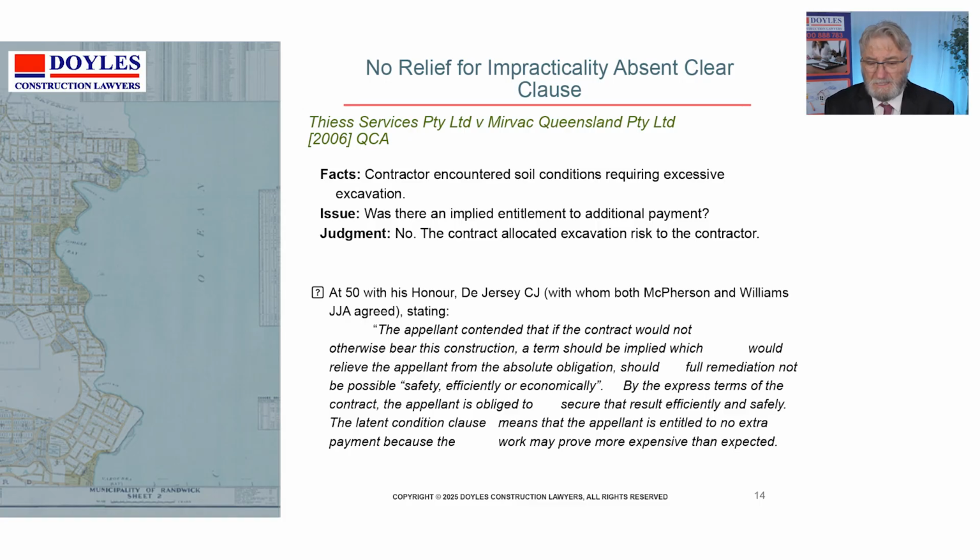He said that if the contract would otherwise bear this construction, a term should relieve the applicant from the absolute problems of remediation. And by the express terms of the contract, the appellant was obliged to secure that result efficiently and safely. The latent condition clause means the applicant was entitled to no extra payment because the work may prove more expensive than expected. So it's important to understand that just because the work will be more difficult, the conditions more onerous, and the resources required much larger, they'll not have sympathy from the courts.